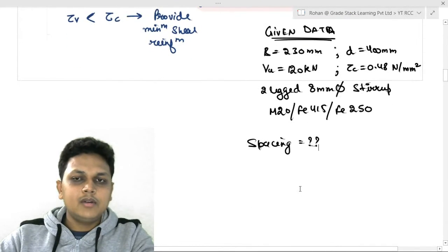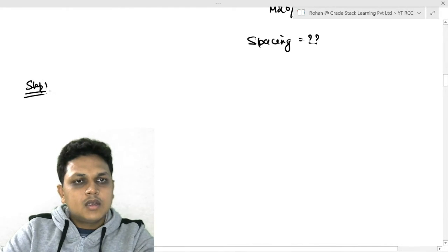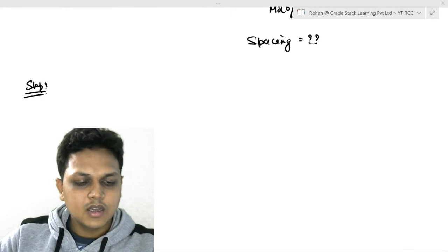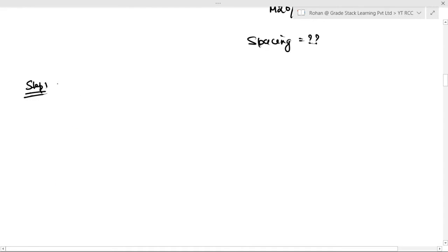So step one, we are going to find out the nominal shear stress, tau v, which is equal to Vu upon bd.